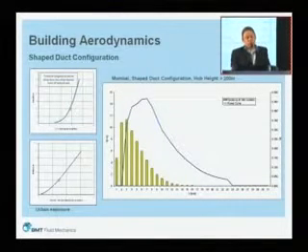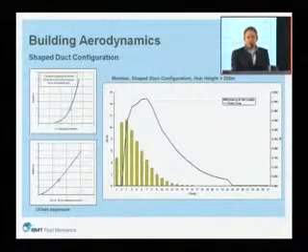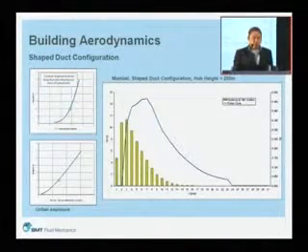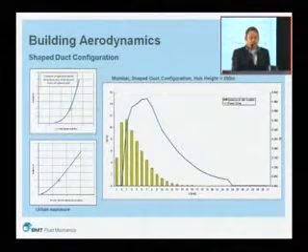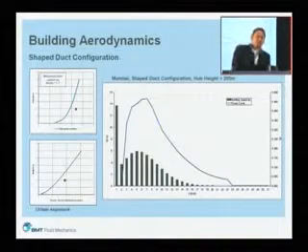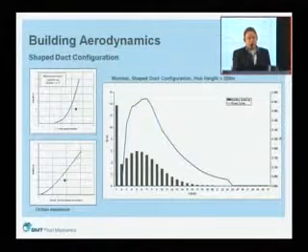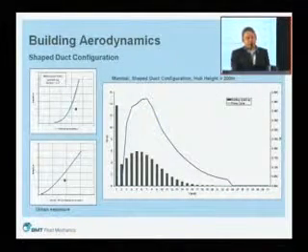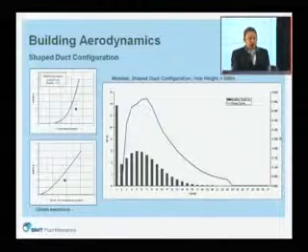When you put in the duct, you need to consider that, assuming that your wind turbine doesn't rotate with the wind, there'll be some wind angles for which the wind turbine doesn't see wind, so it's reduced from what is theoretically available. That's why the green curves have gone down relative to the red curves. You then have further duct losses to consider. But you can see in a duct the general shape of the available wind speed starts matching up to the shape of the turbine.